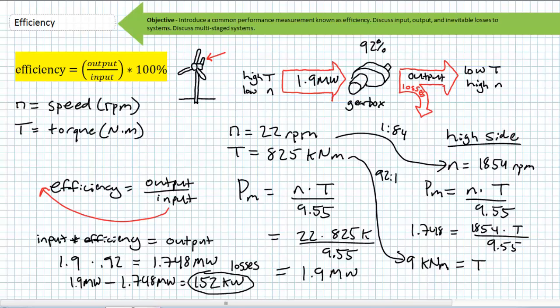This means of cooling is especially cunning because it's almost a passive means of doing so. Think about it. When do you need to cool the oil in a wind turbine gearbox? When it's windy. The wind is turning the turbine and acting as a fan for an air-cooled heat exchanger. This is the same reason a 1970 air-cooled VW Beetle doesn't do well in a traffic jam in July. It's not moving and the heat isn't dissipated. Ask me how I know this.